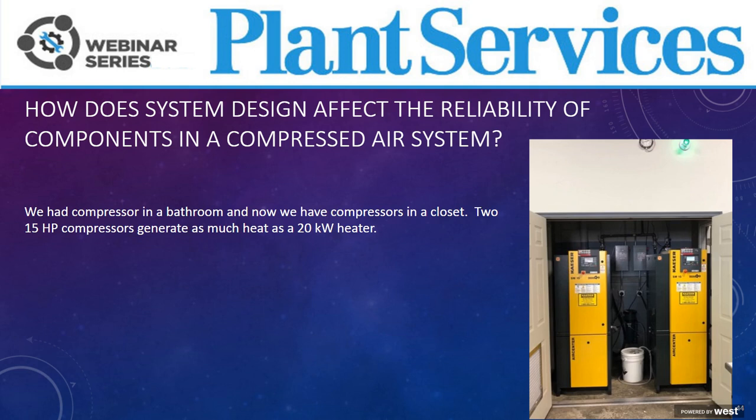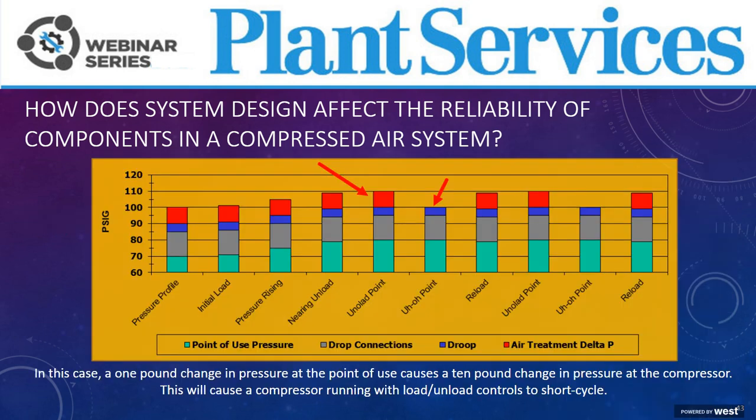Go back a slide. What happens in situations like this is the compressors will load and unload in rapid cycle, just like Neil was talking about rapid cycling. We have instances where we have measured literally millions of cycles in a 6-month period on a compressor, when the cycle time should have been in the hundreds or the thousands.